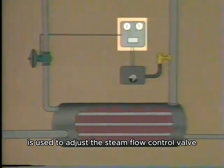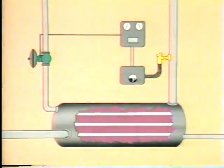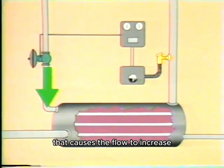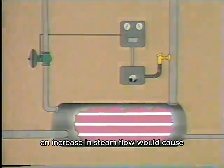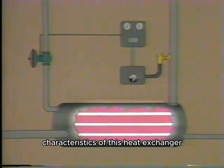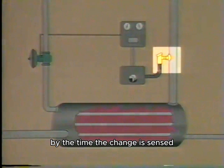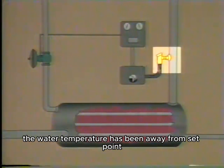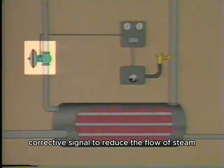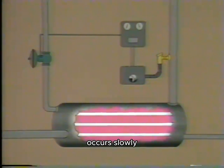Now, this information is used to adjust a steam flow control valve that controls the flow of steam to the exchanger. Let's see what happens if we have a disturbance in the steam flow that causes the flow to increase. An increase in steam flow would cause the water temperature to rise, but because of the lag characteristics of this heat exchanger, the change would be slow. By the time the change is sensed, the water temperature has been away from set point for a fair amount of time. Even though the control loop provides a fast corrective signal to reduce the flow of steam, the change it causes in the water temperature also occurs slowly.